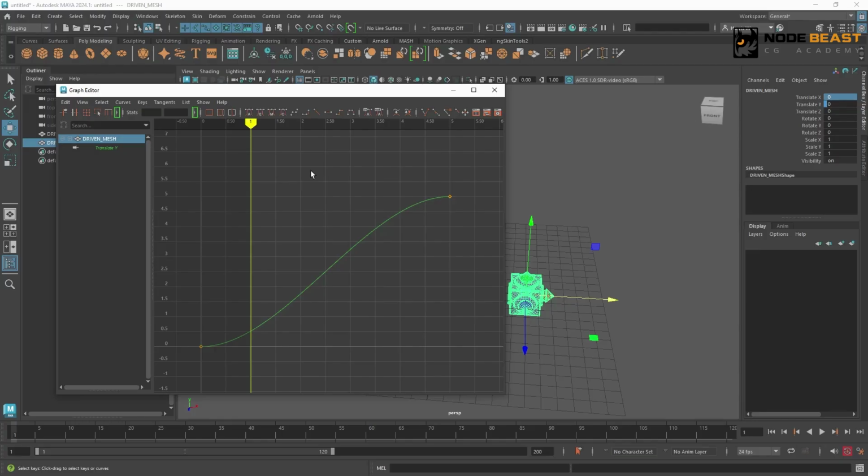Because our course has limited time, if we're not very familiar with the graph editor's operations, I'll suggest finding some animation tutorials to watch to see exactly how to adjust things in here. Here, let's just talk about some of the ones we use most often. First is that we can change the shape of the curve. Look, when I select a point, it has a manipulator handle. This handle, we can also use the middle mouse button to change its tangent direction, and in doing so, change the shape of the curve.